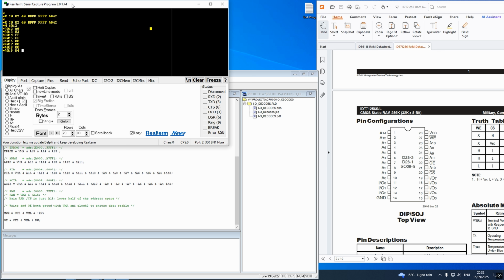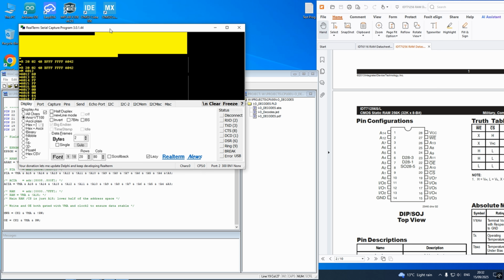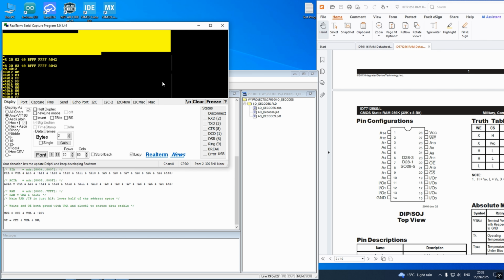I'm quite surprised it is working, because the serial interface is rather horrible, to put it bluntly. It was designed to work with 1488, 1489 series RS-232 interface ICs, and the receiver on the 1489 is open collector internally, so it could be overridden, even though it's directly connected from an output on the 1489 to an output on this. But, let me find the circuit. I'll show you. Oops, it's trying to scroll things.